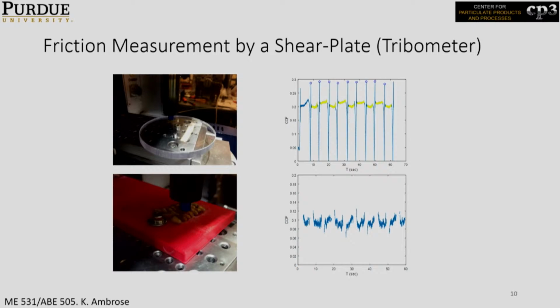Again, this is from one of my past research. So we wanted to measure the friction on wheat kernels. Okay, so you measure the force when the surface moves over the wheat kernels. And again, it's not a large range of movement. It's a very small movement, like 5 micron, 10 micron movement. And then it's kind of back and forth movements, and then you can get friction coefficients. We use the same setup for friction measurements and also wear on surfaces. How much you lose when two surfaces come in contact, mainly from friction effects.